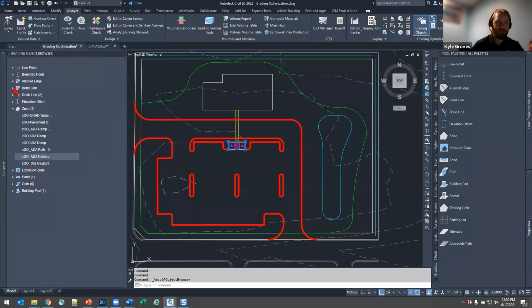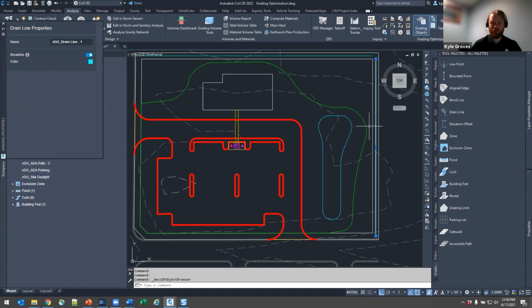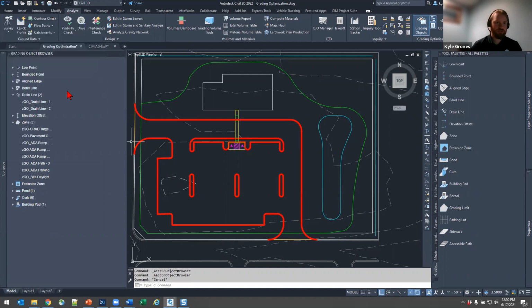So I've got a couple of drain lines, just these two site-wide ones. When you're drawing your drain lines, it's very important. Your first click is going to represent a high point. Your low click, your farther along click is going to be the down point. So just note that you can have a compound polyline, but you're always working from high to low with these drain line features.